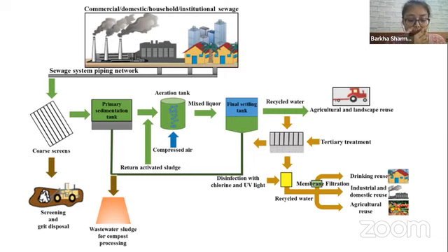Examples of secondary treatment can be activated sludge and trickling filters. They degrade complex organic compounds into non-toxic components. Photosynthetic organisms like plants and algae are used as they generate oxygen to break down these toxic components.